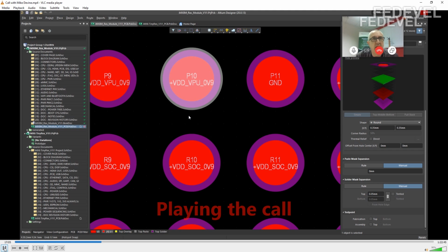The only constraint really is time, because to fill a through via with copper could be anywhere from 24 to 48 hours. Wow. So it is also much more expensive than epoxy fill. Cost-wise, it's not massively more expensive.